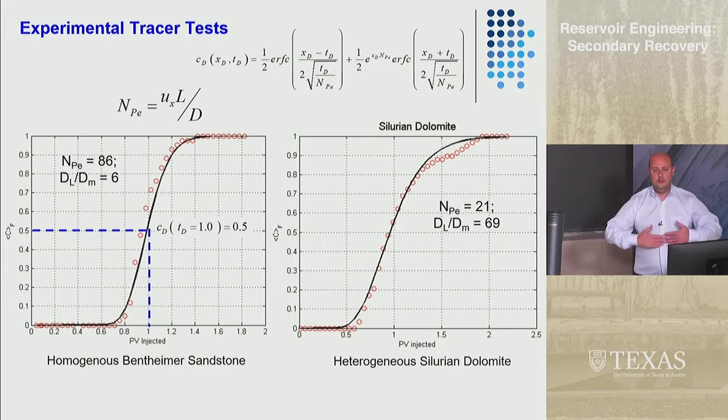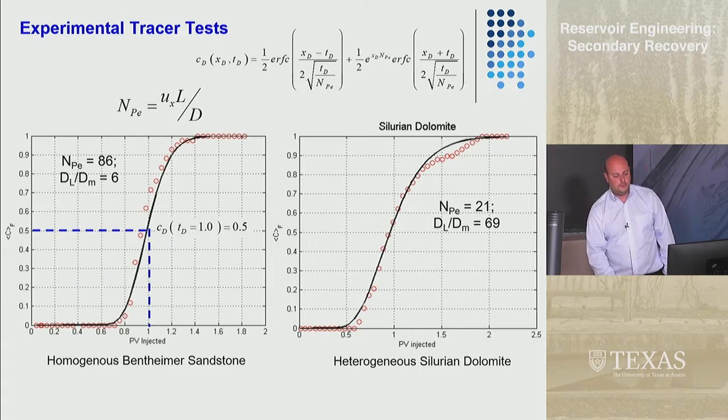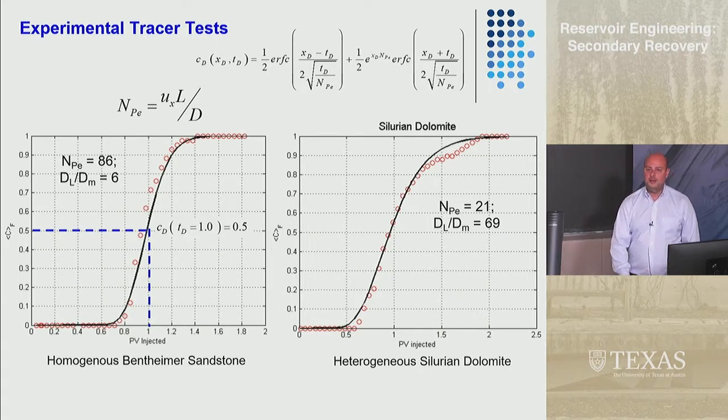You want it to do this, as I've described before, this nice moving wall like a piston, and to push everything out. But if you have heterogeneity, that leads to dispersion or mixing, and then you get an earlier breakthrough, which is unfortunate. And we're always looking for new ways to minimize that effect.